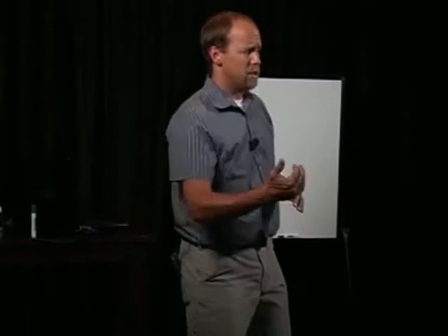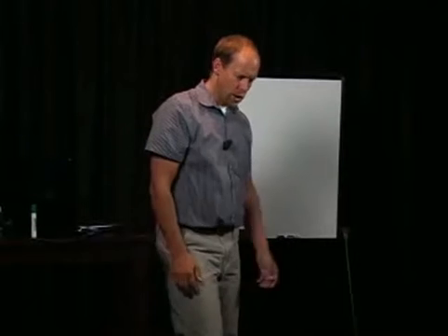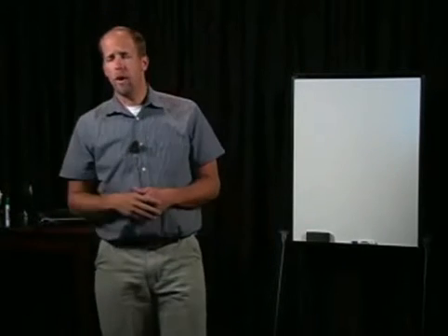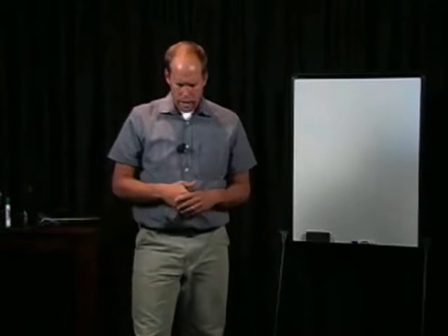And use a carpet for placing right in front of the crawl space access opening. So when you come out of the crawl space access opening, you can brush your feet off a little bit, put down your tools, and you're not damaging anything. Some crawl space accesses are through the floor, not through an interior wall or a perimeter exterior wall. They could be inside the closet. So when you come out, you're inside someone's closet, inside someone's home. You have to be really clean. Laying down a piece of carpet is a really great idea.